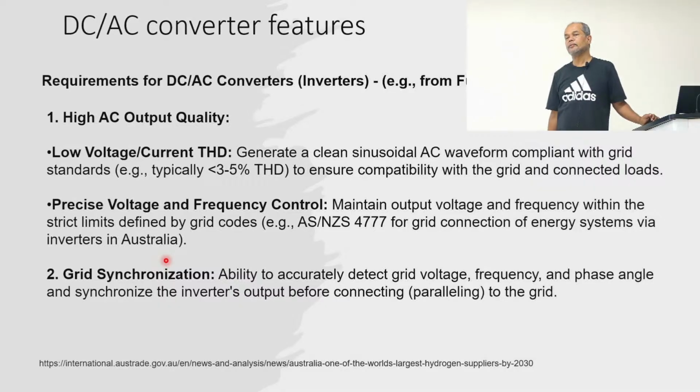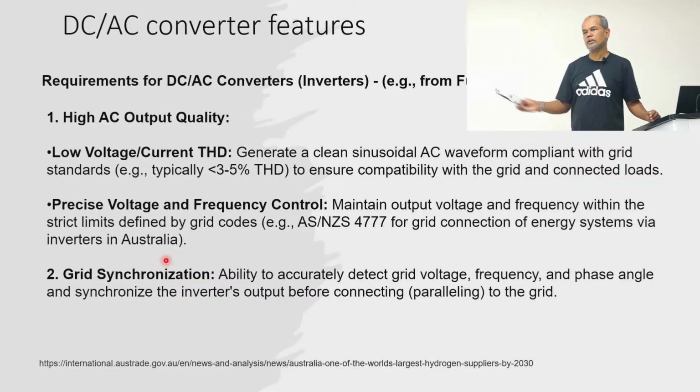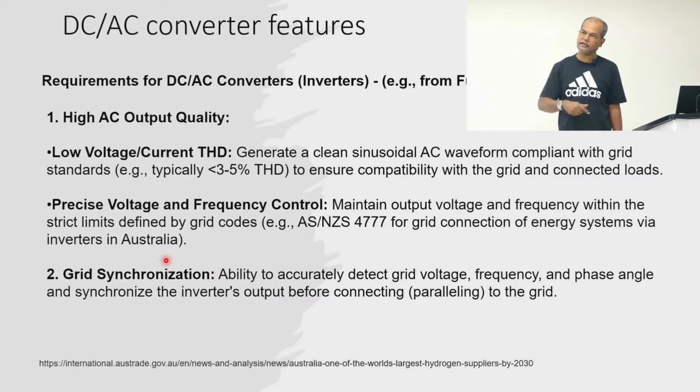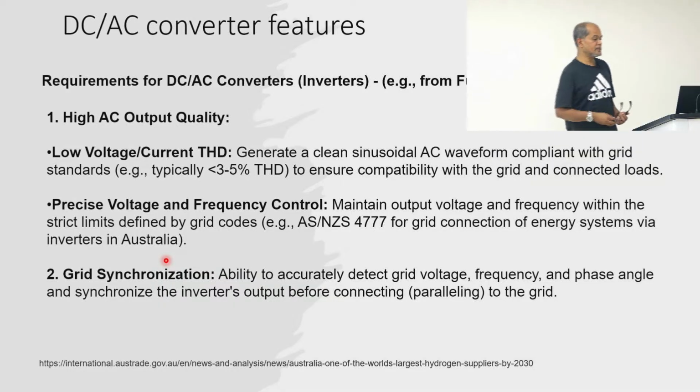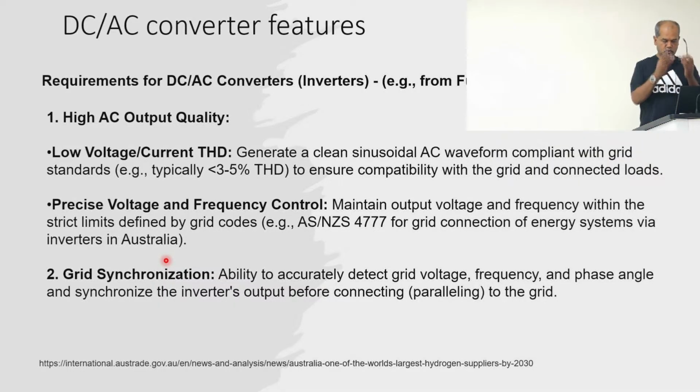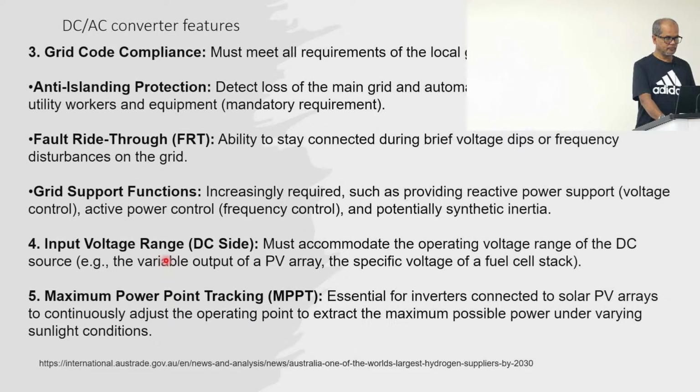And mainly for those of you who work with microgrids, when a microgrid goes from grid connected to island and vice versa, it should have the capability to go from islanded to grid connected, so that it can automatically synchronize with the grid as well. And I believe you know the requirements for synchronization: voltage, frequency, phase angle, everything has to be the same.